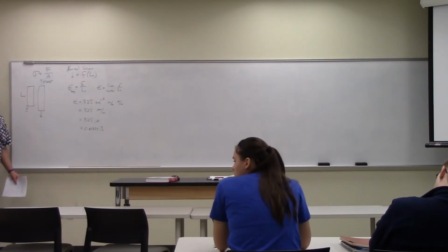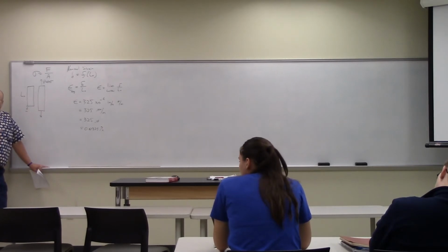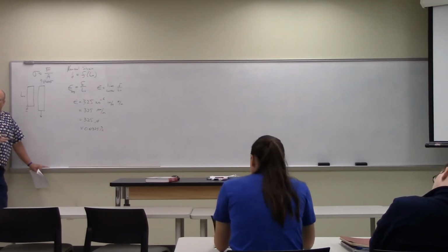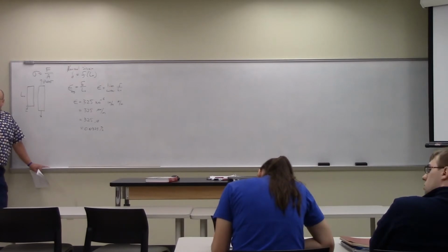If you have a member and you are hanging something from, let's say, a hole in the center of the member, and it's pulling it down so that it's deforming slightly, is that a combination of stress and strain, or is that just strain? So the deformation is strain. The applied load is stress. If there's any deformation, then the thing is strained. If there's any load applied, then there is stress. So there would be both. The stress and strain go together. You always have the two together. You can't get a strain without a stress.